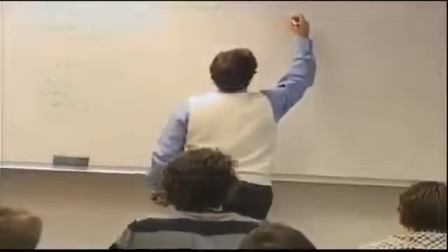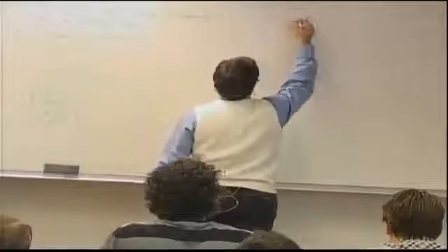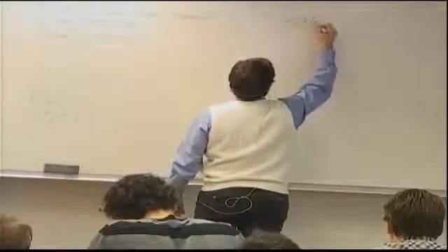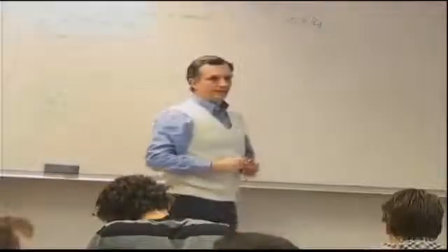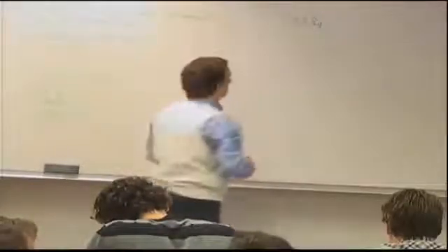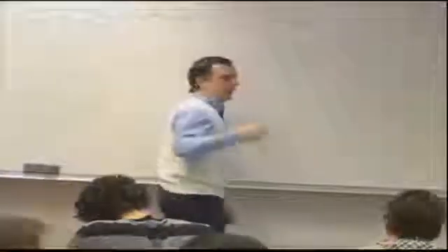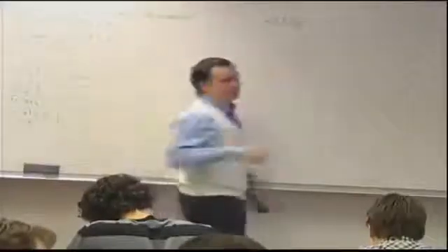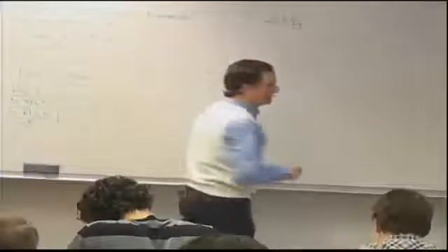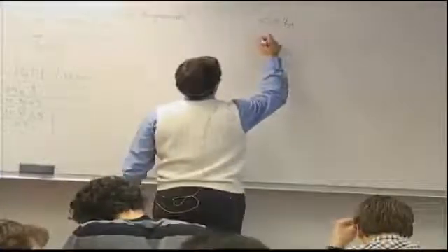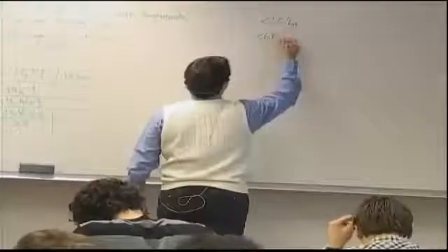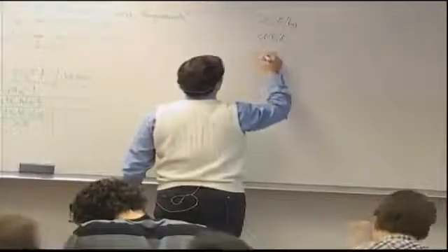In fact, the numbers, just for now that I'm thinking about it: if you're doing your regular family car, then it's less than 2 euros per kilogram of weight saved that the manufacturer is willing to pay, because that translates to certain fuel savings and so on. If you're doing a higher performance car, but not Formula One yet, so it would be between the electrical cars and higher performance top of the line, then it's less than 6 euros per kilogram. Formula One approaches 20 to 50.